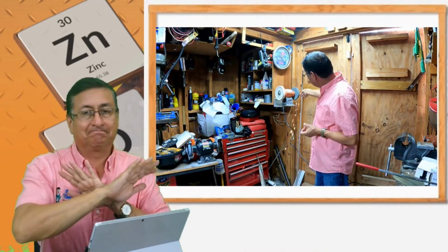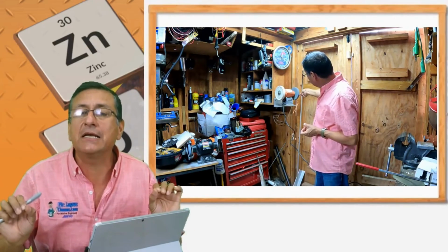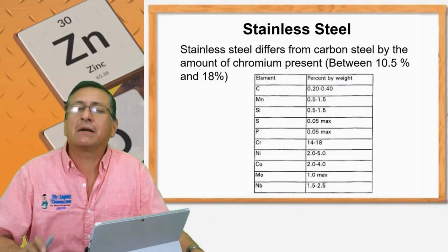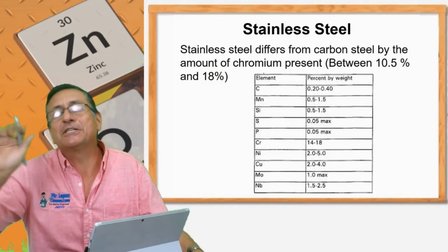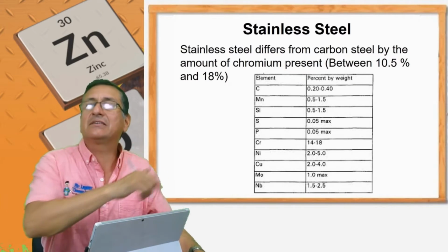Remember, iron is the only metal that produces spark when you pass it close to the grinder. With non-ferrous alloys, you can pass them to the grinder: no spark. Aluminum, no spark. Copper, no spark. Non-ferrous, no spark. Ferrous alloys, yes. The only one with practically nothing is stainless steel. The pure stainless steel, marine grade especially, zero spark. Not zero, 0.0 something. But it's practically nothing. This is another indication that the steel is not good.